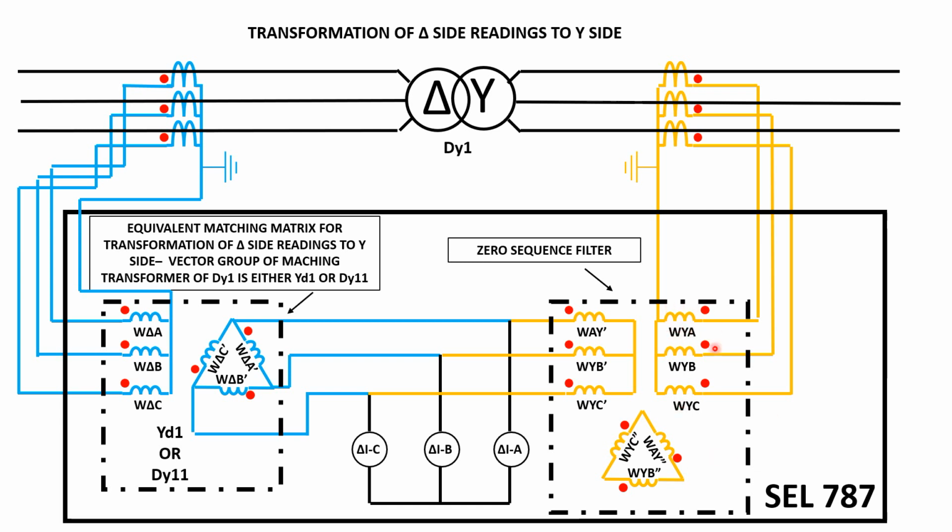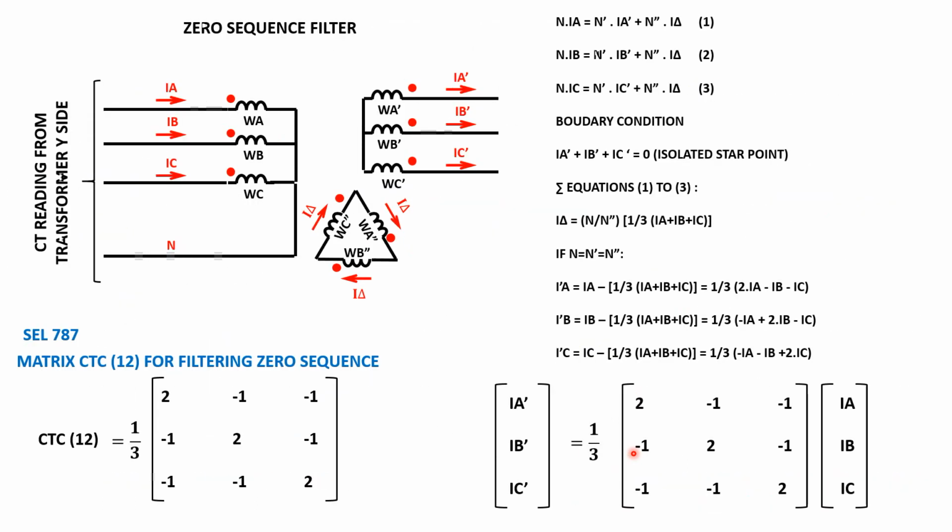So any readings that come here include a zero sequence. The output doesn't have any zero sequence, and the zero sequence will be taken by the closed delta. It's in the equations here. So with this arrangement, remember there is no connection, isolated neutral here. When you're writing the equations here, you can pause and look at the equations, but at the end this out current is the in current minus zero sequence current for each phase. So we have this equation.